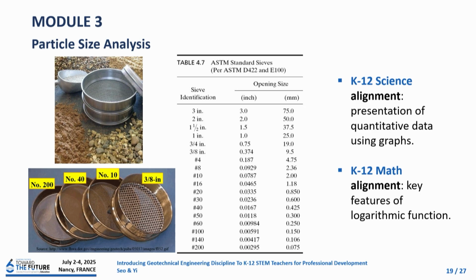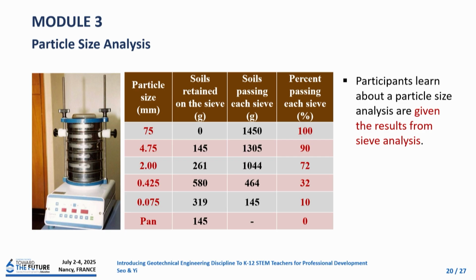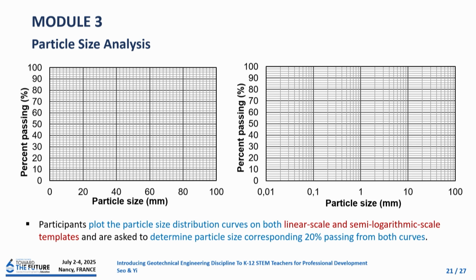So we briefly introduce sieve analysis, and I give this data sheet from one of the textbooks, and they calculate percent passing, and I also provide some guidance. And then I ask them to plot the result of this sieve analysis on two separate graphing templates. One is a natural scale, and the other one is a semi-logarithmic scale.